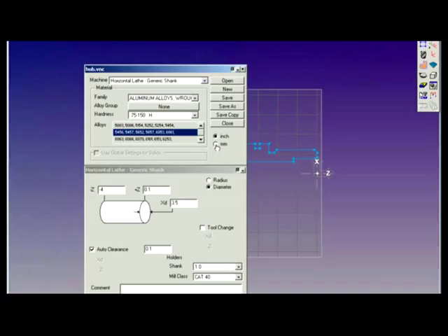If you have to do a conversion within the program, it's best to do the conversion on one of the dialog windows and divide or multiply by 25.4 to get the conversion. The global settings for solids remains grayed out because, as I mentioned previously, we do not machine solids in production lathe.